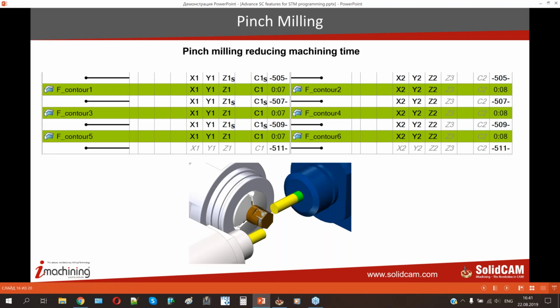The last axis combining mode I would like to describe today is simultaneous machining. Simultaneous machining means that two tools are cutting one part together simultaneously. In comparison with balance cut, these tools do not share the same operations. Both tools have their own operations, for example, turning and drilling, but because they have to operate on one piece of the part, they have to share the drive unit and or one axis, depending on the situation.